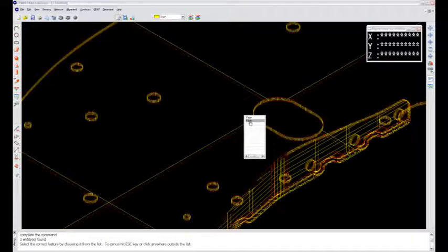Let me go down to the next one there. And again, I'm seeing both sides material, like in the cylinder and in the holes, and on the upstanding flange. They are all red. Okay, well, I don't like that so much. And on the CAD side of it, there may be options inside of SolidWorks or Pro-E or CATIA or Unigraphics or whatever CAD system that you're grabbing your files from, that when they do an export of the step, they can give you individual surface patches and wireframe content.